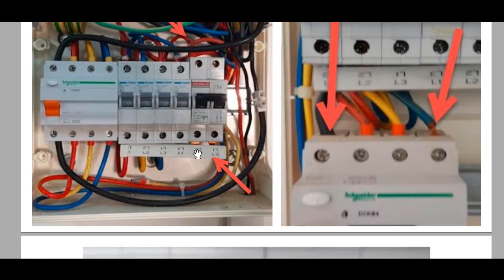So in this case, before they install this one, these two Havells circuit breakers must be removed and changed to Hager, or change all of them to Schneider or whatever, or change to what you have in your store to make all of this one set. Therefore, and then you are going to install the line bus bar.